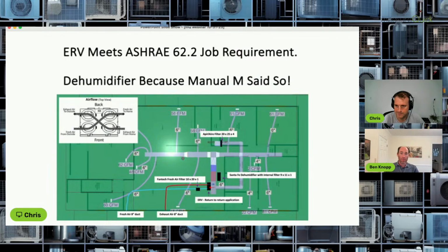You mentioned keeping equipment clean. I used to work for John Semmelhack, and he put MERV 13 on his equipment soon after installing it, and takes pictures every few years inside the return ductwork, where he can see the back of his air handler with the blower, and it's just shiny metal.